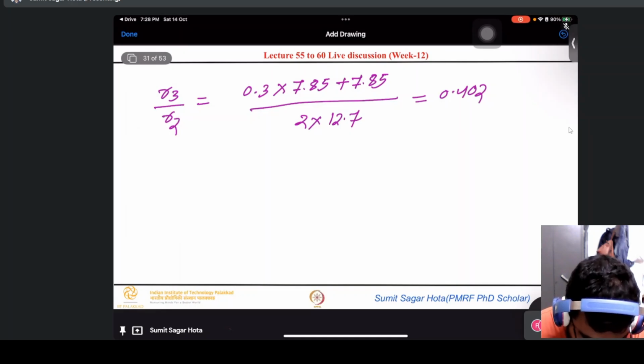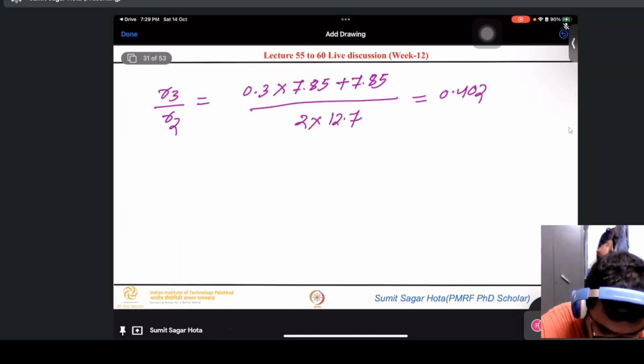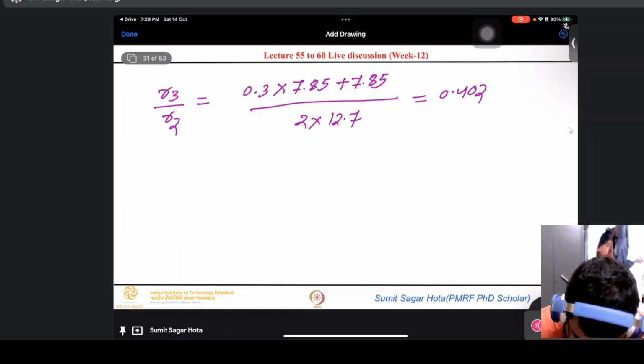Now, eta t also has one very good formula which relates to lambda r. What is lambda r? It is your rotor loss coefficient. The rotor loss coefficient and lambda r have a very good relation that we just have to substitute, with some angles, the nozzle efflux angle alpha 2 and beta 3. All these are included directly in the formula, and I directly write down the formula using the values.